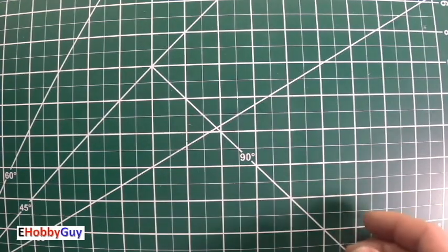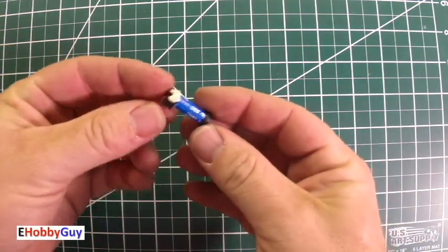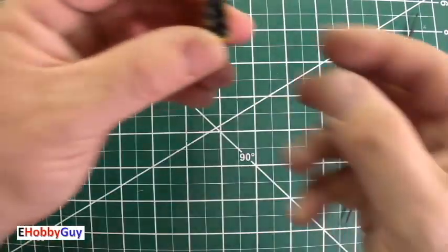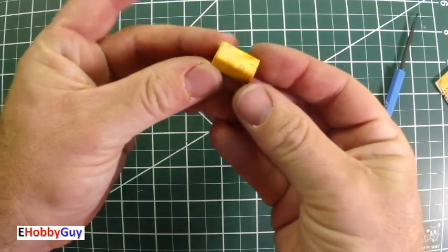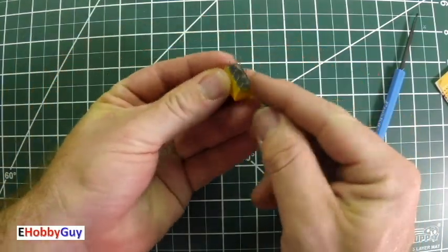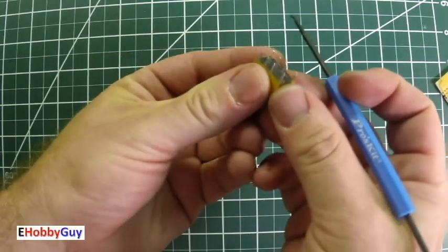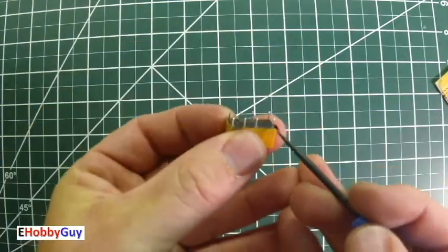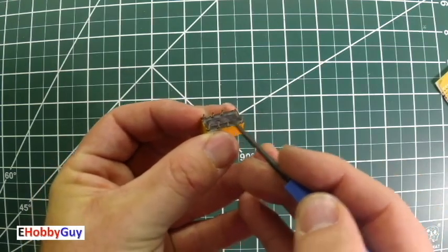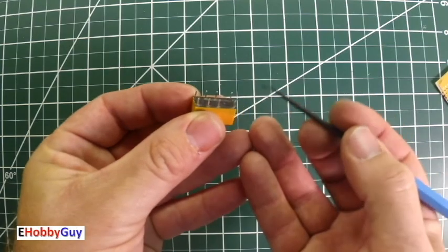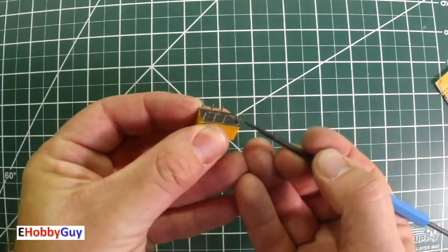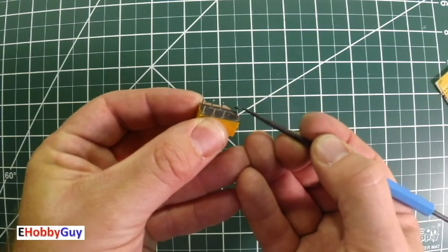Okay, so let's take a look at some different types of relays here. It's a Form A PCB mount relay. Here's another PCB mount relay, and you can see this is a double pole, double throw. It may not be too clear in your picture, but you can see these two terminals at this end are separated from these three. This is just helpful information, but most likely this is the coil. And a good quick way to test would be to put a meter on these two terminals.